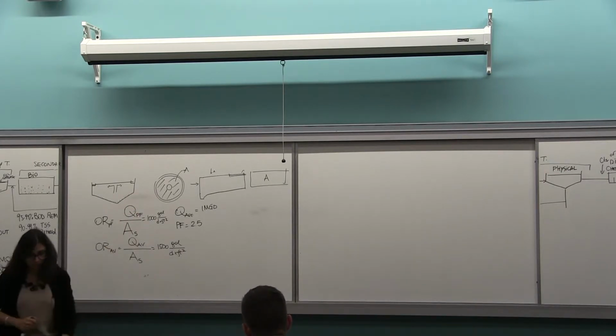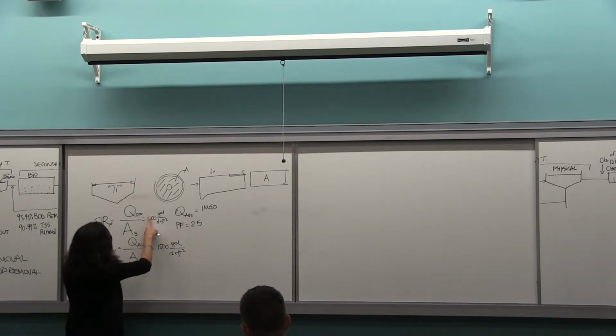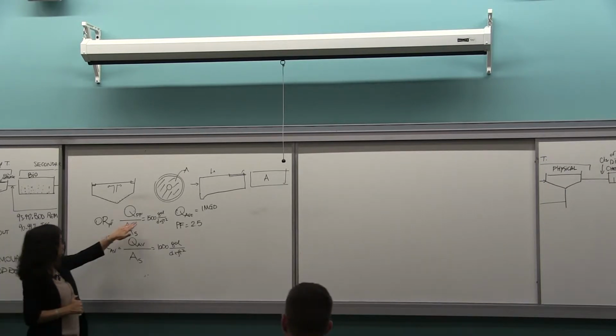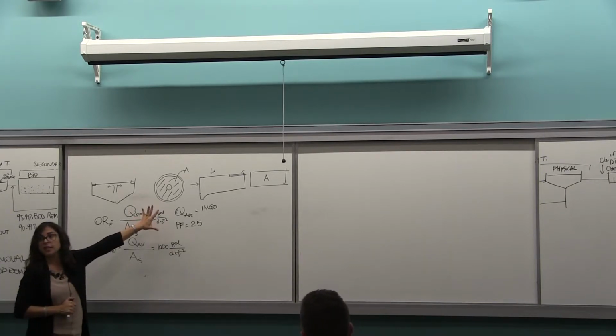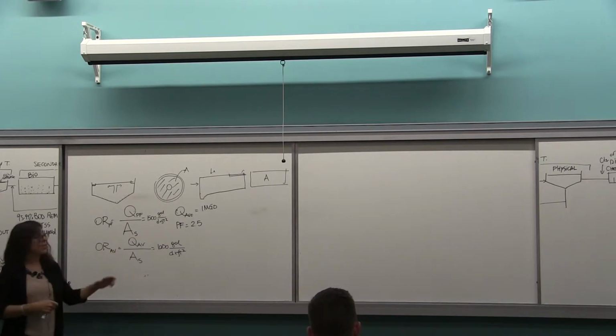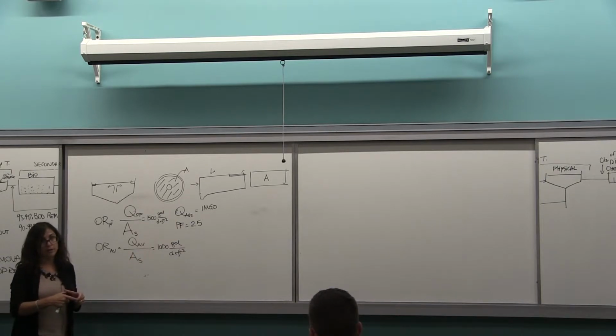Oh, did I invert it? Yes. I considered this average. This is 1,500, this is 1,000, right? Under peak flow, you can only treat 1,500 gallons for every square foot of area. Under average flow, you can treat 1,000 for every square foot of area, right?